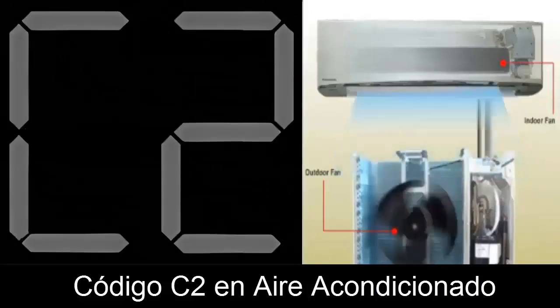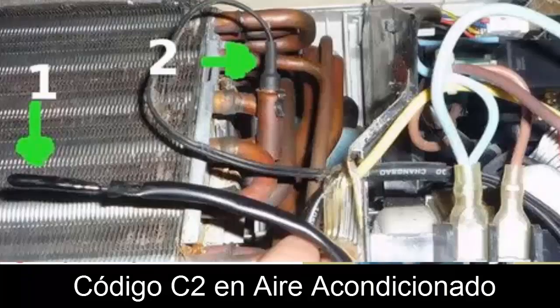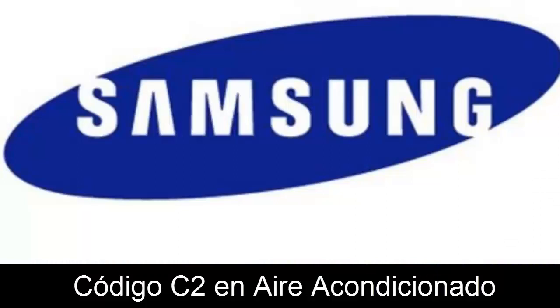2. Failure in the temperature sensor of the evaporator tube. This interpretation of the C2 code is used by the Samsung brand. To solve the problem, follow the same steps described above for a temperature sensor, remembering that in this case, the electronic board managing the temperature sensor is the indoor unit's board.